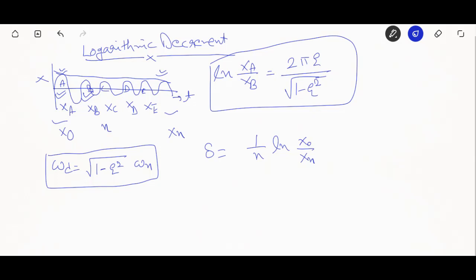So if you are dealing with the underdamped case, we will certainly go down to damped natural frequency, which is again a function of damping factor, and it represents the amount of damping present in the system, which would bring down the system's frequency from the natural frequency.